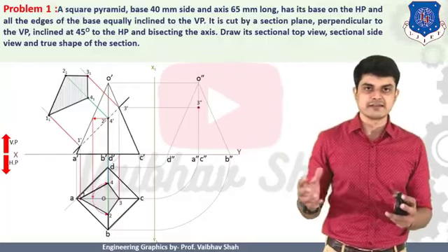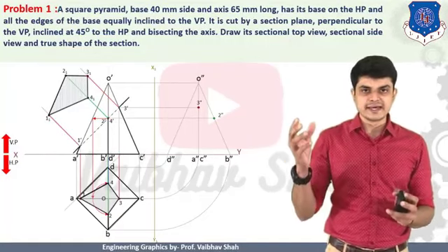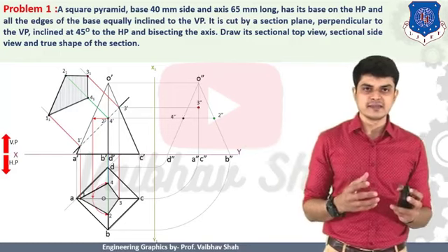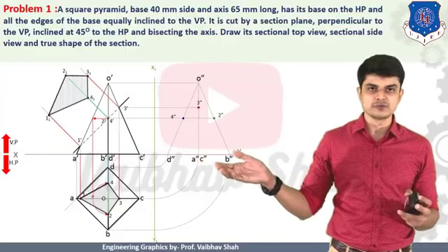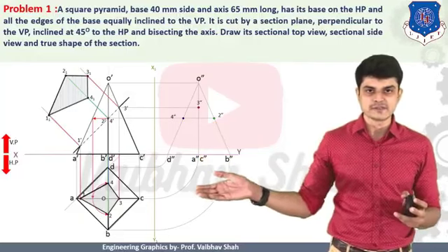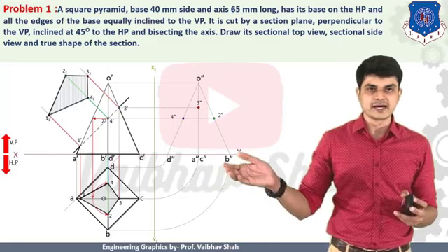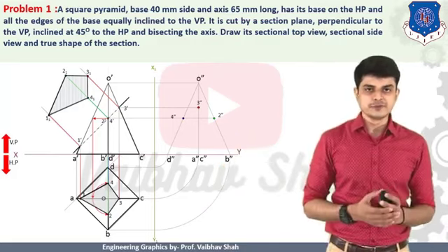So let us transfer each and every point horizontally like this, and then we should mark these points, 2 double dash and here 4 double dash. These points can be found by drawing the horizontal line from 4. Then after, you should make one arc and you should go up. You will have a 4 double dash point. You should draw a horizontal line from your point 2, make one arc, and if you draw the vertical line, you will have your point 2 double dash.